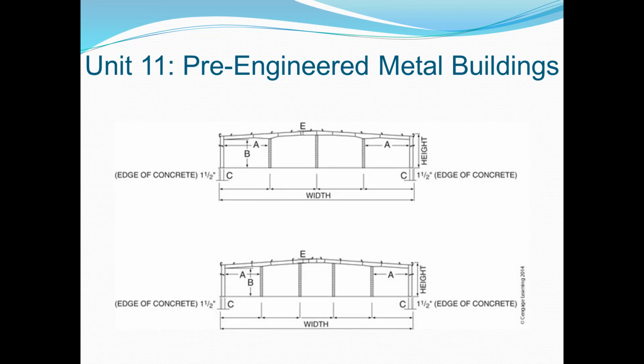So how do we go about drawing the rigid frame cross section? First, we have to find out the appropriate cross-sectional configuration from the manufacturer. Then we go to the chart of the pre-engineered dimensions for the cross-sectional configuration and find the height and the width of the building, and then the weight of the steel. Lay out the rigid frame cross-section and add all the necessary dimensions.